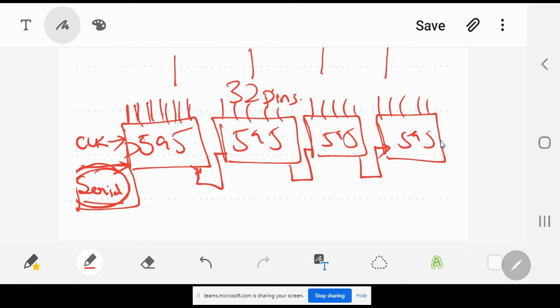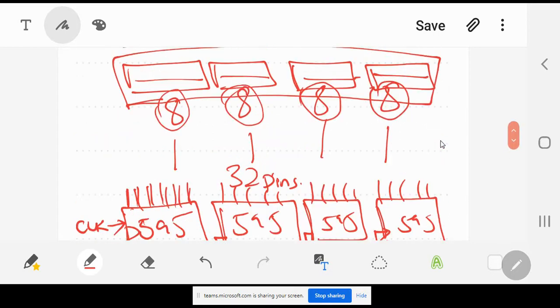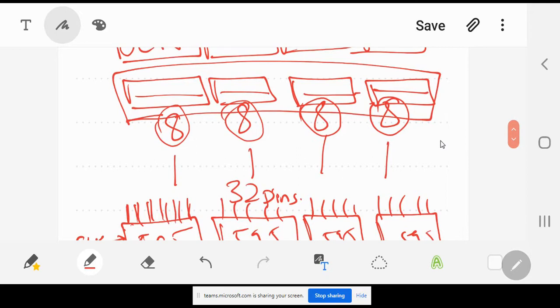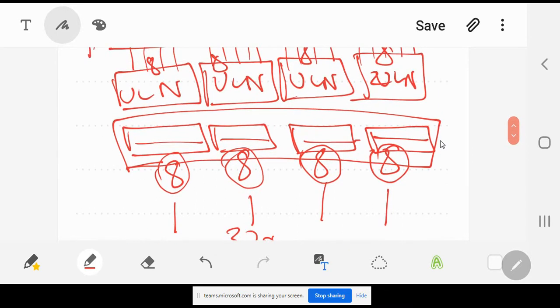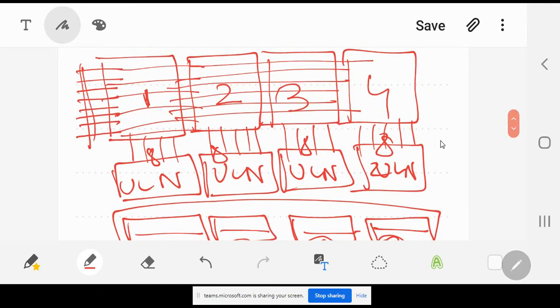Now we are not going to ask you to code this and all that. That code will be supplied by me and by Sir Bilal, so you don't have to do it yourself. The only thing that you have to do is place this IC, connect these 8 pins over here with the input pins of the ULN2803 IC over here, and then make the rest of the connections over here.